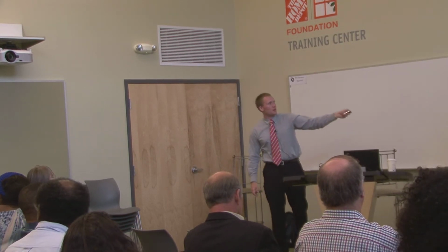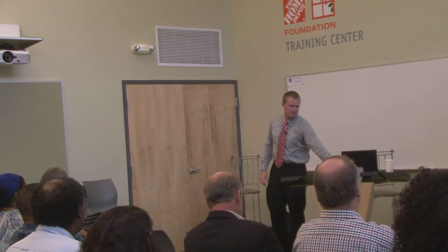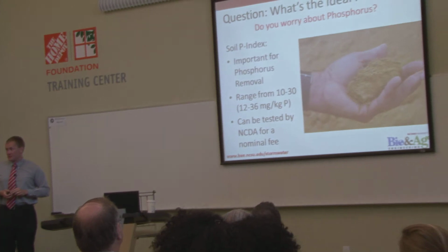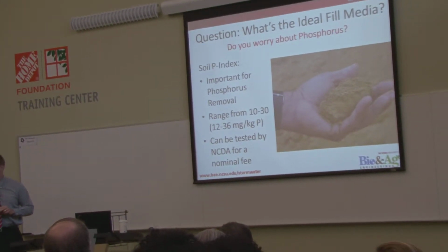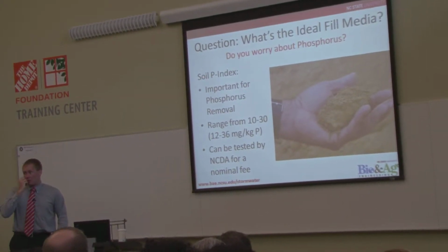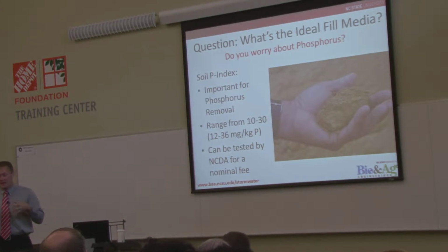So for TSS, you're really fine with a much higher conductivity through your media. Phosphorus is another big one in North Carolina. Y'all don't have too much phosphorus concerns here, or do you? They're in some of our TMDL. Okay. So the key thing with bioretention media with phosphorus is to not get a media that already has a lot of phosphorus in it.